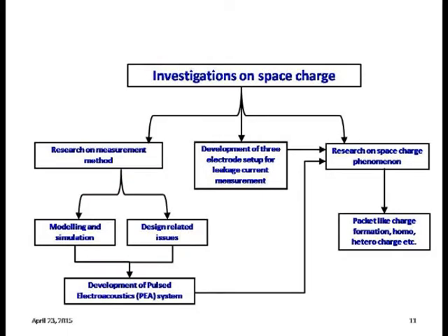So if we can measure leakage current, and from that guess the type of space charge and how the charges are trapped inside the insulation, that will be of greater use. With that purpose, we have also developed a 3-terminal electrode for measurement of leakage current. That is well known in high voltage engineering.